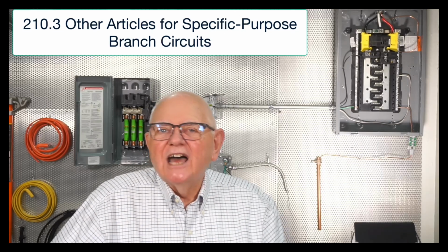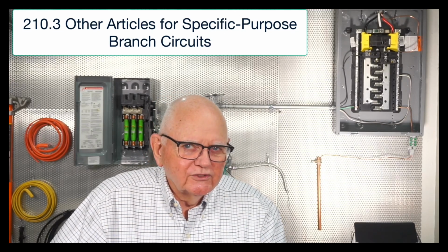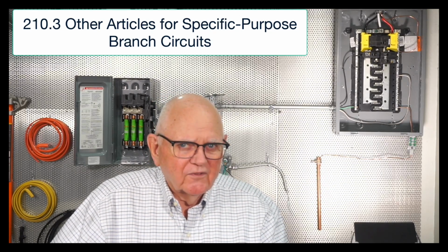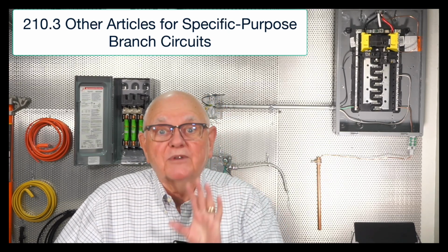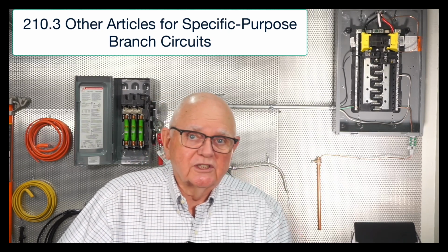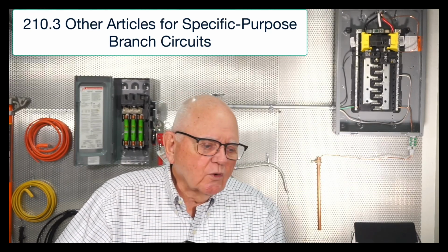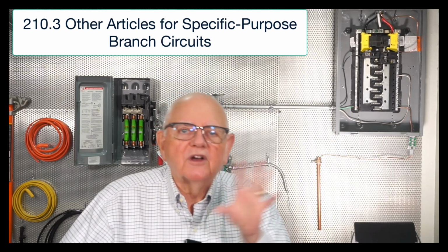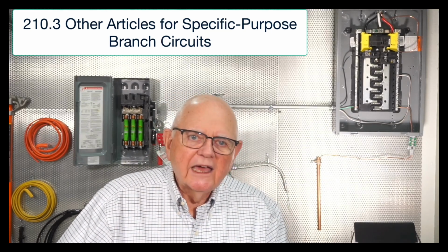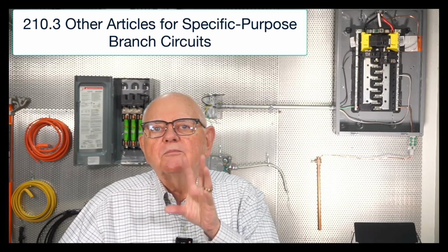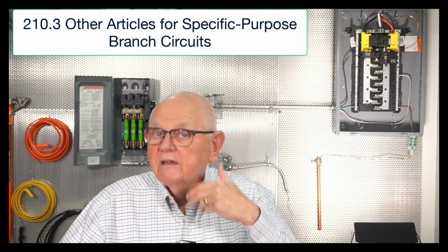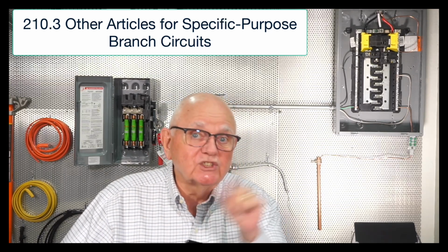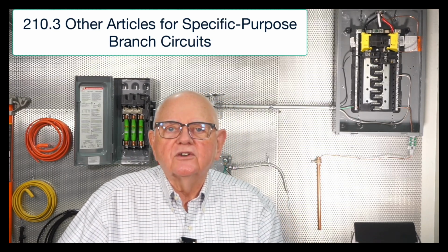Table 210.3 right at the front of Article 210 might be very beneficial for you. It lists about 9 or 10 different specific applications for other branch circuits, other equipment. For instance, if I had a question about motors, it's going to reference me to Article 430. If I had a question about a branch circuit for a piece of HVAC equipment, it's going to reference Article 440 and may well give me the specific sections where I would go to find information on those branch circuits.